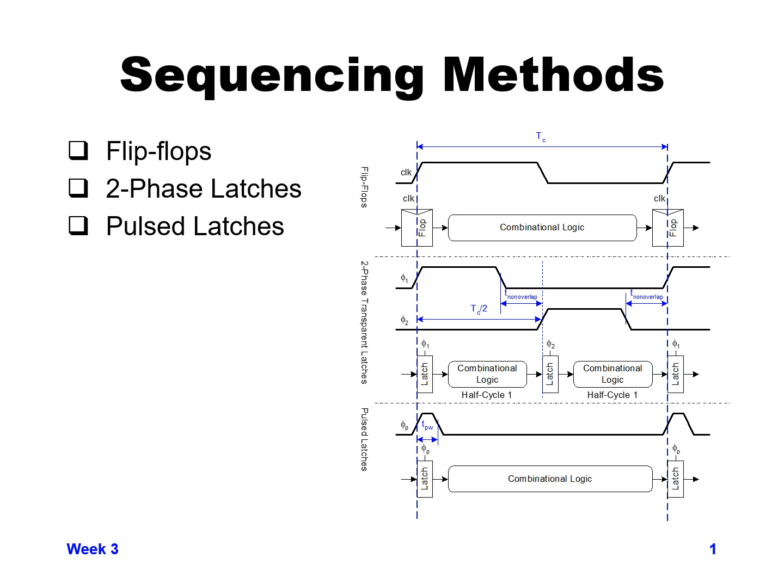Now, by contrast, the next set is what's called a latch design, so a two-phase transparent latch design. In this type of design, we have the input on the far left is a phase 1 latch, and on the far right is a phase 1 latch, but in between we have a phase 2 latch that captures when the clock goes low or when the phase 2 clock goes high.